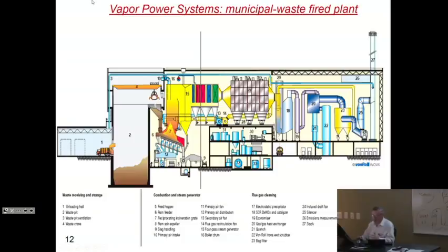Now, other sources of fuel can be used. Classically, waste heat from municipal waste can be burned. So it's accumulated here. The scale is given by the truck there. And that is sent here into your power generator. So this is your boiler and your steam generator. Now, of course, the flue gases of this require very extensive treatment because basically they stink.